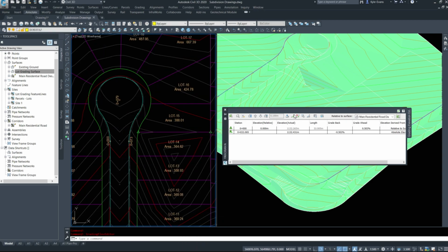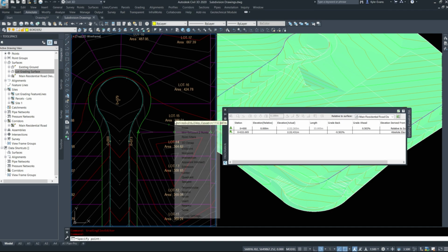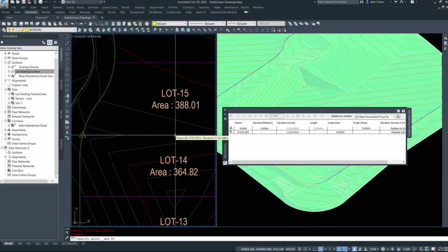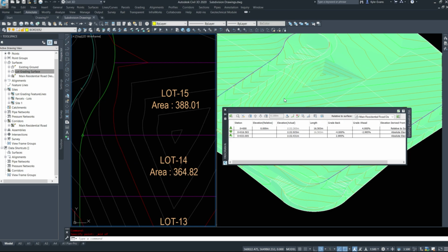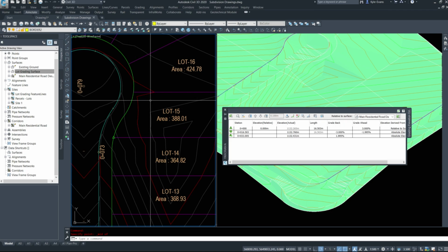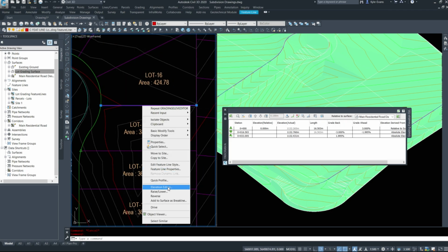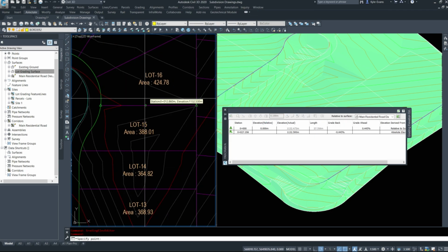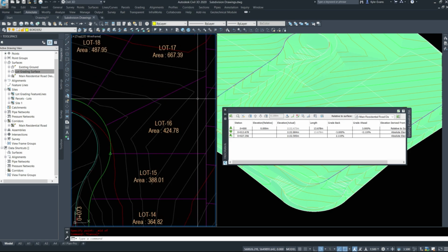If we go elevation, just keep doing them as long as we need to match our slope requirements. 4% up. This one could probably be 3% up. Elevation editor on the next one. Really, it's a lot of rinse and repeat. So if we go 3%, try that, -2 down.